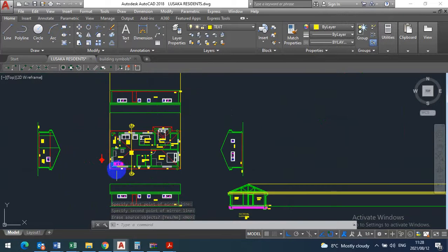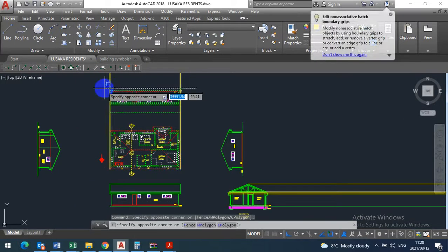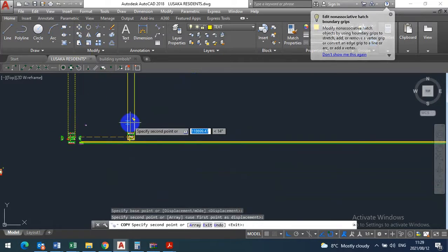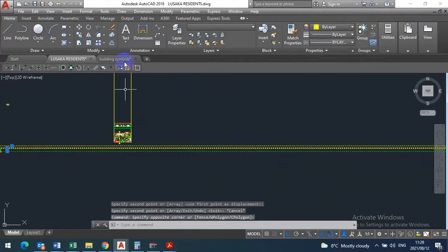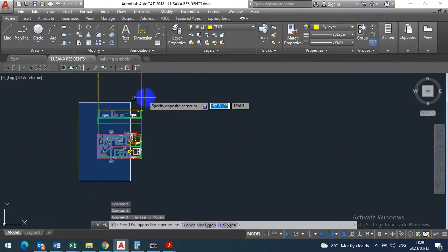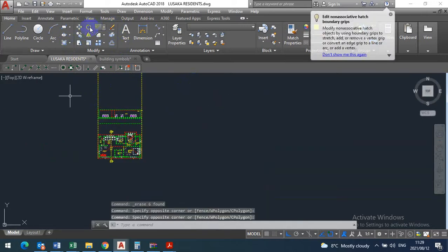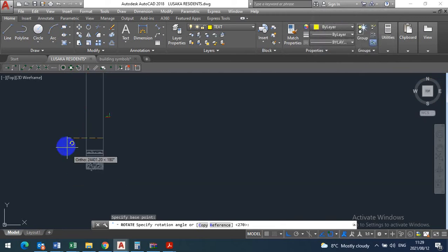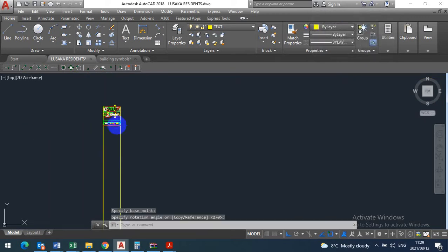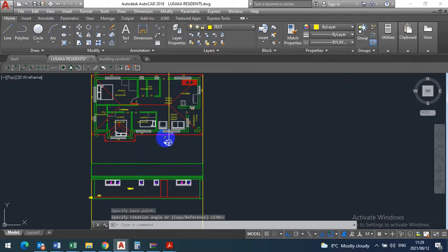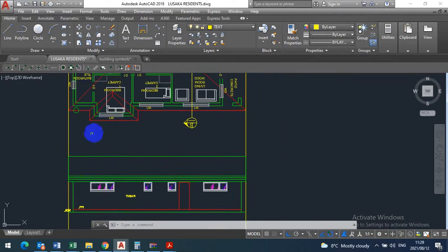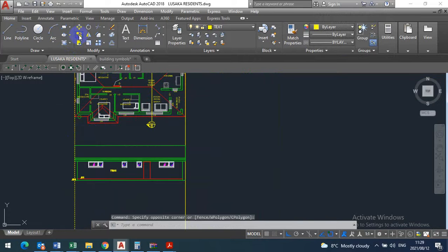So what I want to do, I hope you understand, I'm going to copy all of these. It's just the north. Copy. I'll copy it aside. That side. This we can delete. Then I'm gonna mirror, I'm gonna rotate everything so that I can see nicely. Yeah, like that. I've flipped the entire floor plan so that I see the north like this. This is how it's gonna help you. The rest remains the same, except that there's this roof that I must now show you, not copy.